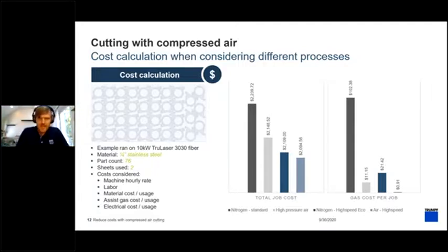When you get into the biggest savings, though, you start using the Highspeed or the Highspeed Eco nozzles. So again, some of the reason that the high speed part here was the second to the cheapest piece, you can see here we're a little bit less than we were with the standard piece. A lot of that's going to come down to the cutting process time, because again, you have the material that you have to consider. That's your big cost. You also have the labor uses, all those sort of things, but of course nitrogen.